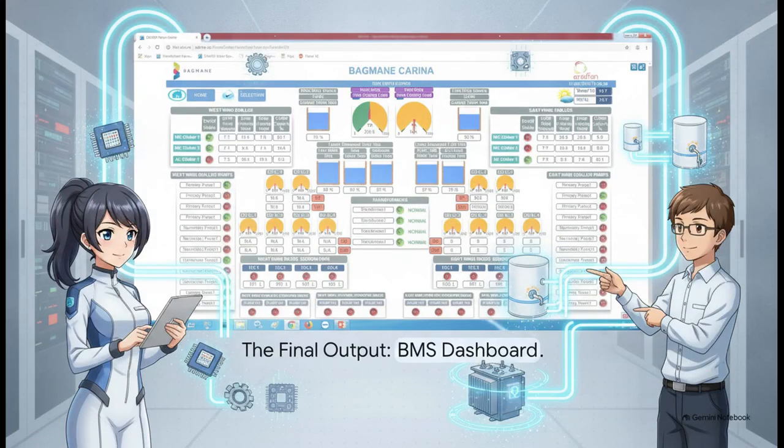And finally, all of this underlying complexity, all those sensors, the muscles, the BACnet protocols, the DDCs we just talked about, it all culminates right here, the BMS dashboard. This is the visual interface, the steering wheel for the facility manager. From this one single screen, they can instantly read chilled water temperatures, monitor the exact load of those cooling towers, verify the domestic water tanks are full, and make sure the electrical transformers aren't overheating. It takes millions of invisible data points and distills them into crystal clear, actionable intelligence.